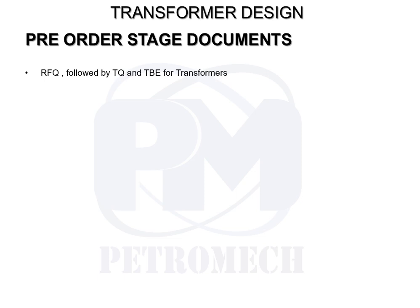It's very important to keep in mind that it is not always that we have to go for T1, T2, T3 for 3 vendors. If one vendor is non-complying on many important parameters in the design, we can technically reject that vendor, because with those parameters we cannot move ahead in our design. So we can technically reject them in the technical bid evaluation stage.